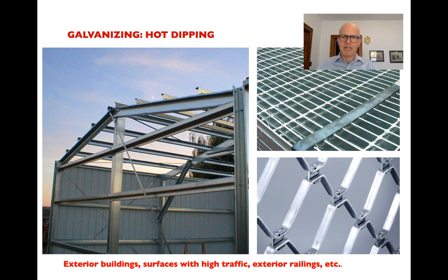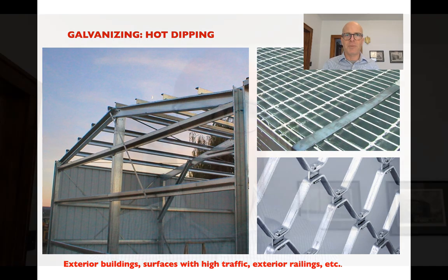And it's also a very, very difficult material to weld because you're welding through a zinc coating on the outside. And that gives off both incredibly toxic fumes and also, of course, violates the zinc barrier that keeps water out. So if we're galvanizing elements, we tend to want to weld them first in the shop, then to galvanize them, and only to bolt them on site.